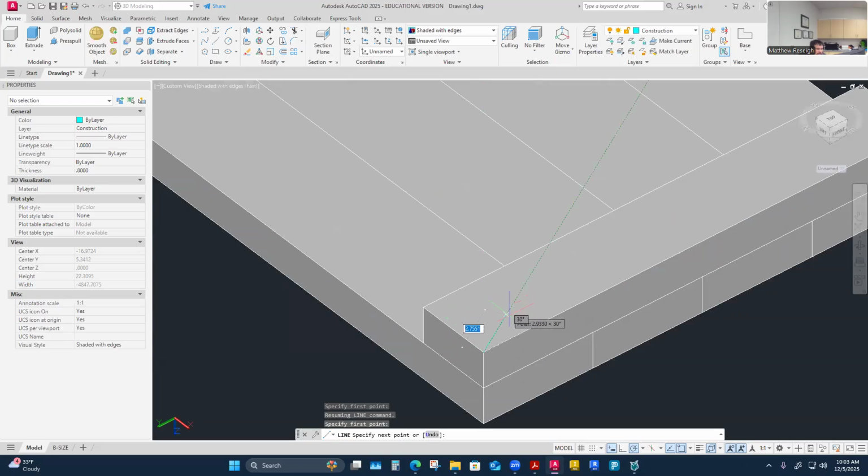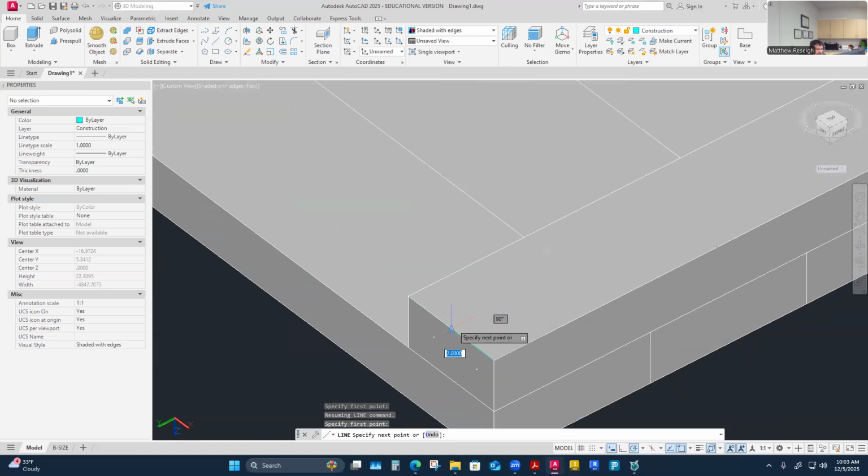You can kind of see my polar snap tracking is going to want to stay on these grid planes in a way. It'll help me stay parallel to that or parallel to this. Just look for those grid snap tracking. And then I'm coming this way. Really, it comes over to the midpoint. I could just snap there, or I could say it's 2 inches over. And then from this direction, if I just stay and look for that 90 degree, there's a perpendicular line that I'm kind of drawing to that. And it's 3 inches over from here.